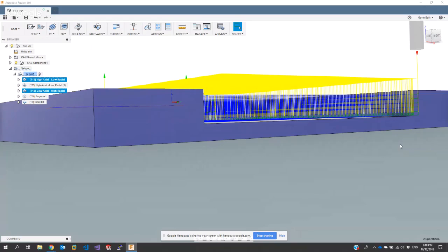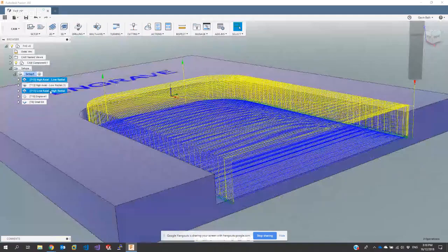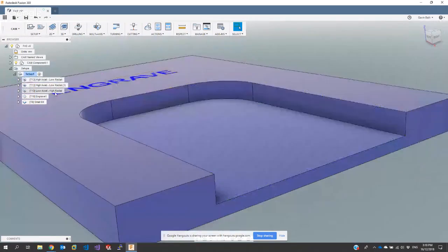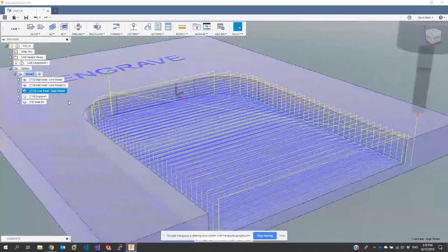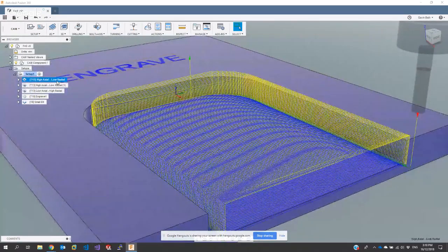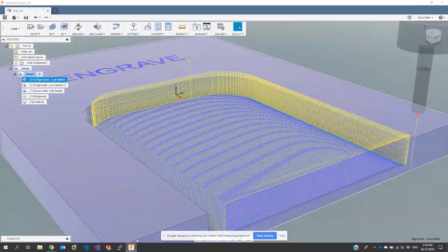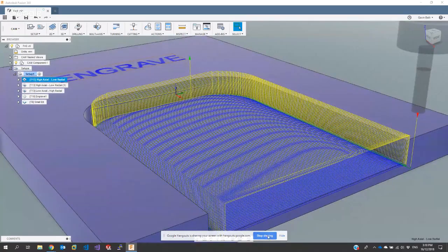And in softer materials, woods and plastics and things like that, the effect on tool wear is not going to be as significant either. So I tend to prefer the low axial, high radial on a desktop router, and on a milling machine, I would always go high axial, low radial, unless it was a really complicated material, like super duplex or something like that.